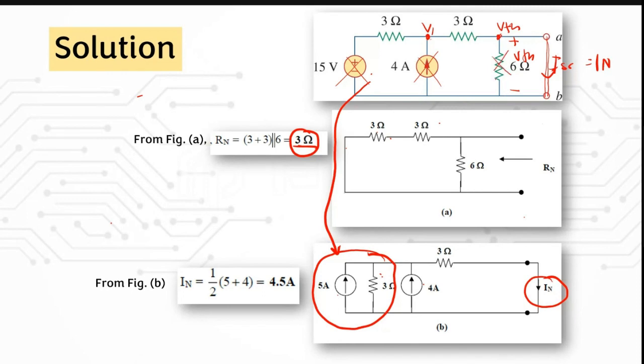So you can just ignore this resistor, and then redraw your circuit, where you don't have the 6 ohm resistor, because when you put the short circuit current, there is no connection for the 6 ohm, as there is no current supply here. So that means you can use this circuit with the source transformation. From this part, it will transform the current.